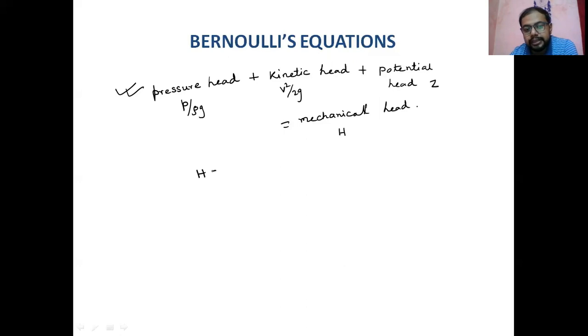So under this assumption, mechanical energy is a constant when it is an inviscid flow, steady flow, constant density flow, and whether it is rotational or not, along a streamline, and gravity is the only body force.